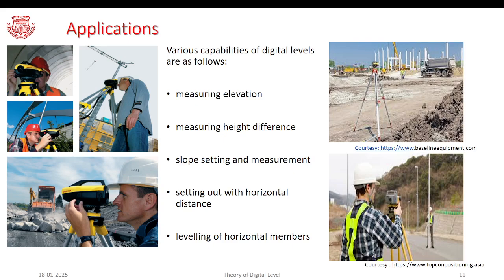Even as this particular equipment has the stadia interval as well as distance measuring capability, we can set out the horizontal distances. Even we can have the inverted staff readings in order to have the horizontal platforms at various levels in level condition.